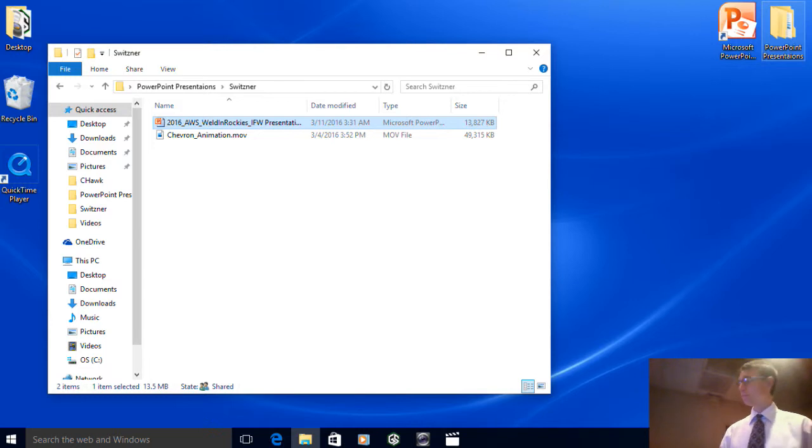So when you look at an ASTM designation, they give sometimes fairly large composition ranges, whereas if you look at AISI designations, they're very narrow composition ranges because they're based on the composition of the steel, whereas ASTM is always based on mechanical properties. ASTM is based, and ASME is based on mechanical and chemical. But they also oftentimes put chemical specifications in there. Not always, but oftentimes they do.